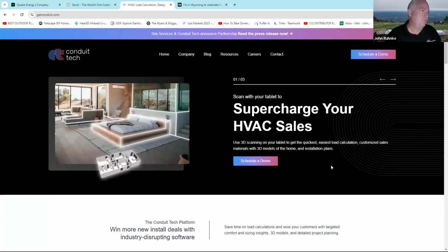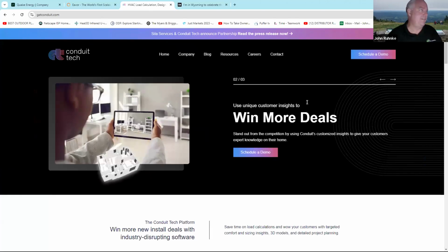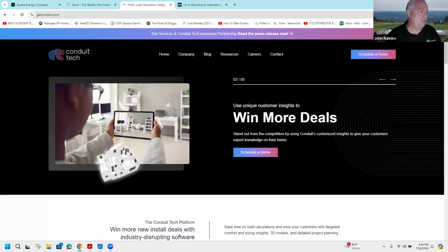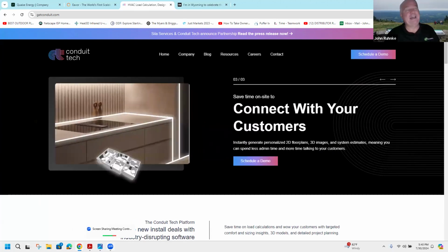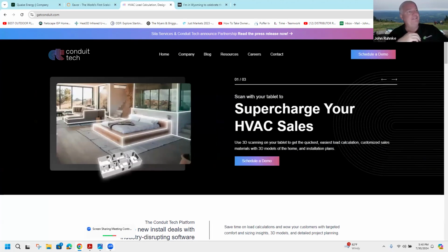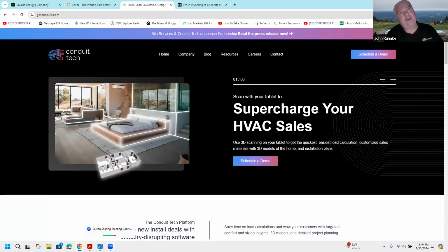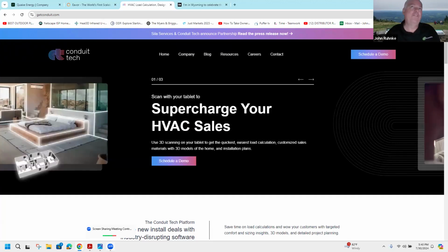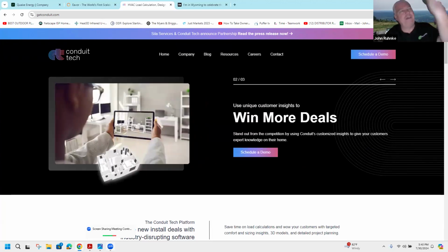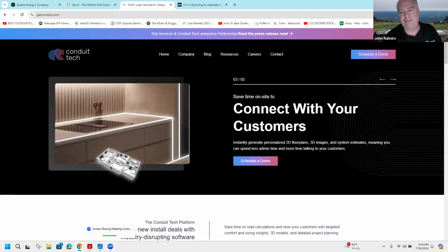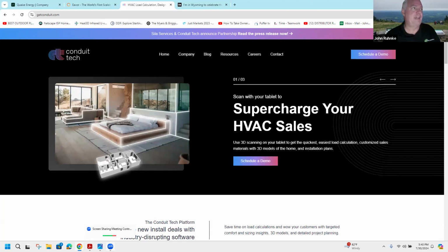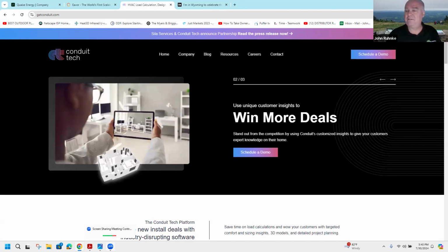You're done. So then all that information can be put into a database. And then that database, that's where you can compare. You could say, okay, the efficiency of this house is, let's say, 80%, and then this house next to it is 60%. And then you could put in like thousands of houses into the database. And then you could say, let's bring out all the houses that have foam insulation and see what their average efficiencies are. Then you could bring out all the houses that have batt insulation. And you could see that foam insulation outperforms batt insulation by about twice as much. And then from there, you could modify the Manual J heat loss software to actually improve upon it, to say, you know what, because foam is always outperforming batt insulation, let's give it a higher R value in the future